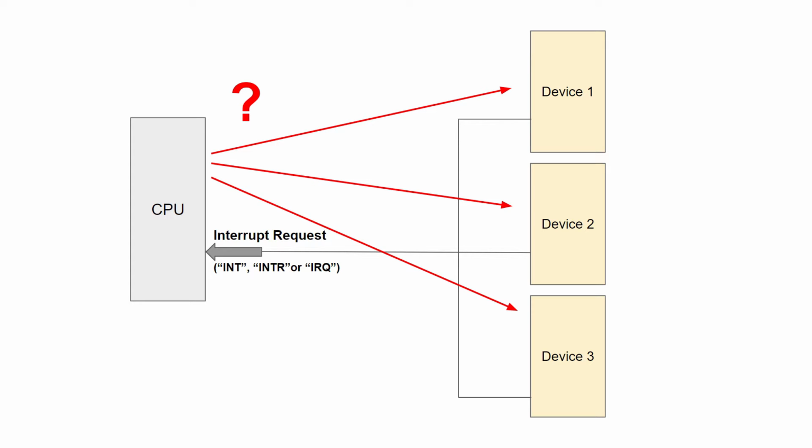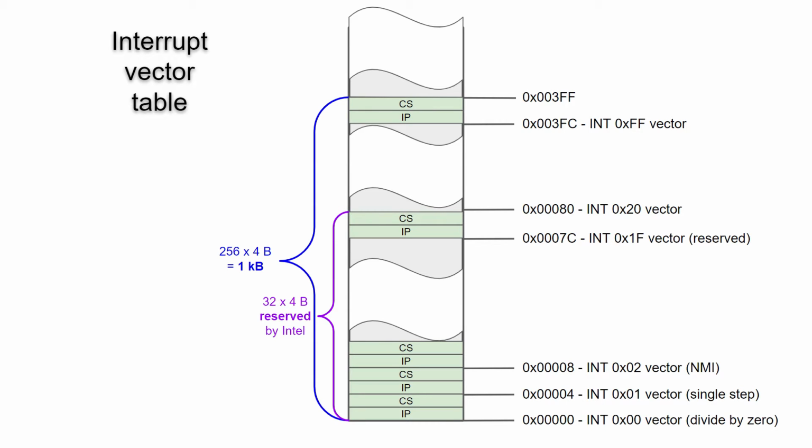It is slightly more complex in the 8086. We have not 2, apart from the reset vector, but 256 distinct vectors to be allocated for each device. To make it even more complicated, the interrupts may be raised not only by the signals on those 2 pins of the CPU, but also by the CPU itself or by the software.